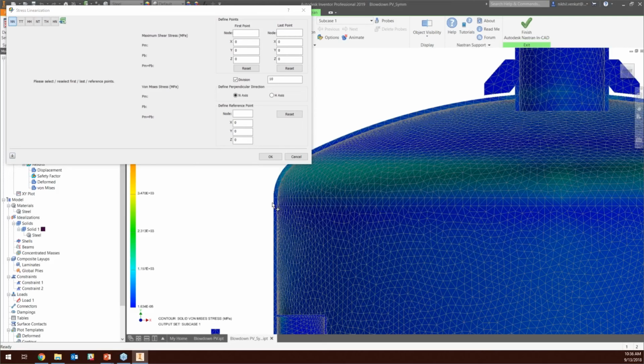Let's see. More information on analyzing weldments. Is there a way to analyze different types of welds? So welds are another animal entirely. You don't analyze welds as welds. I was talking to Nikhil about this when Nikhil started here, maybe almost a year ago now. The way you analyze welds is different, right? You imagine them as other things, or you use line elements. Line elements for welds as well.